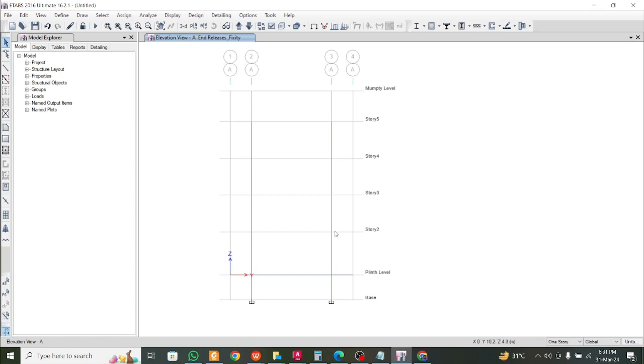So for the next floor, this is interesting. Now the primary members, I think we don't need to copy. We can copy, we don't need to do it again. But before that, with all the secondary beams, if you want to assign a different property for the secondary beams, we can do that. But for the plinth beam, we'll keep the same, or we can assign the property which we assign to the cantilever portions as well, in the portion of the secondary beams, at least in some portions.